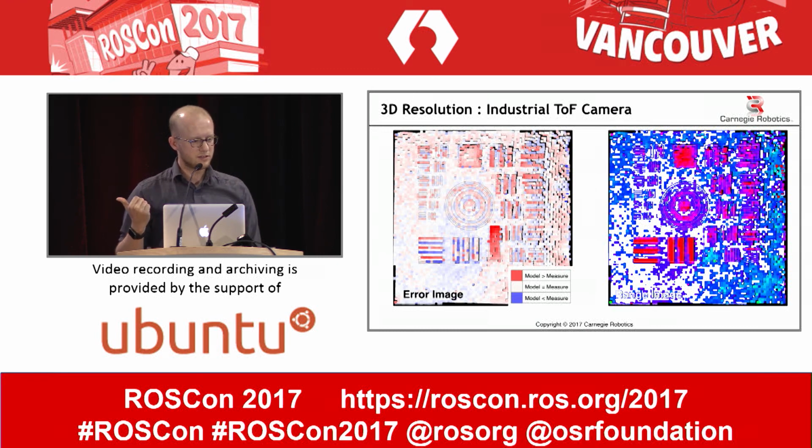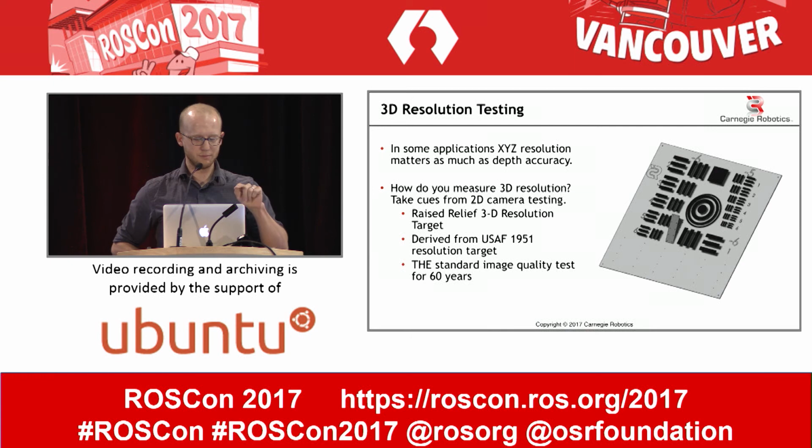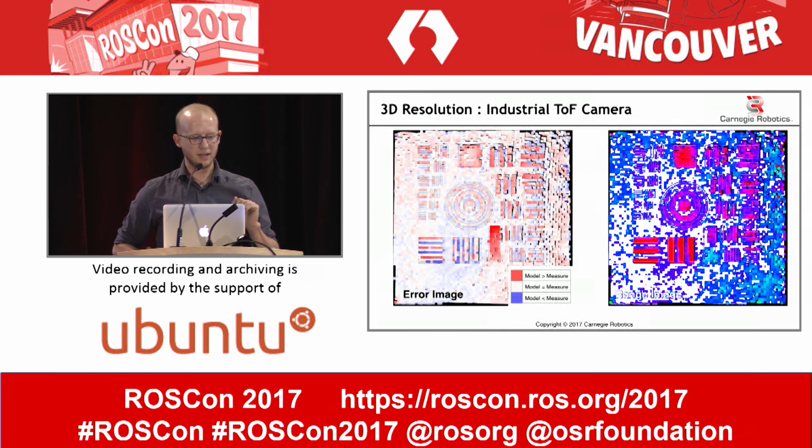And this is what this target looks like through an industrial time-of-flight camera. You see horizontal and vertical bars. The left image is an error image. White is the model and the measure lining up. Red is the model is in front of the measure, and blue is the model is behind the measure. And then on the right side is just a raw range image showing a 2.5D height map. One thing that's really interesting in this is we added this slanted target you see below the bullseye, this sort of a 3x6-inch wedge on the target, and that totally disappears. You really can't see it in the range image.